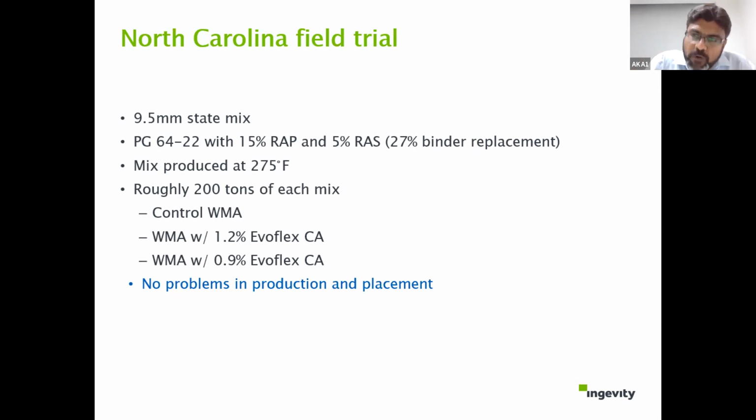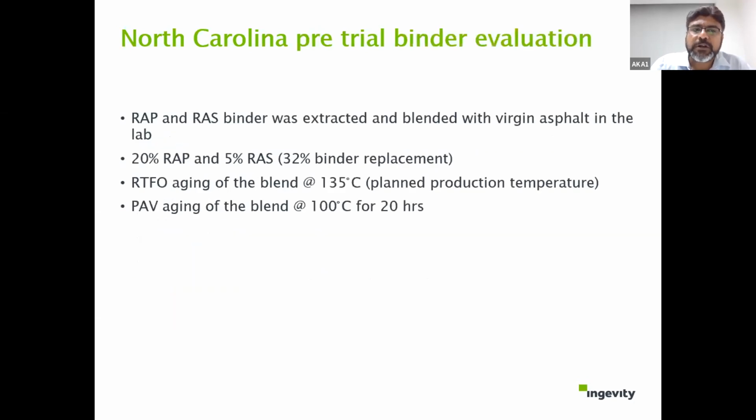When you start using more passes, what typically happens in the field is that the aggregates get crushed. So there is an optimum even in the number of passes. If it goes beyond 7, 8 passes, you are in fact damaging the whole aggregate skeleton. Even a core taken after 10, 15 passes will not represent the Marshall mix that we make in the lab, because aggregates are crushed and you'll find more fines. So if I want to finish it in 7 passes, I need better workability, a better binder, one which is more ductile. Hence those criteria decide how much dosage of these products is used.